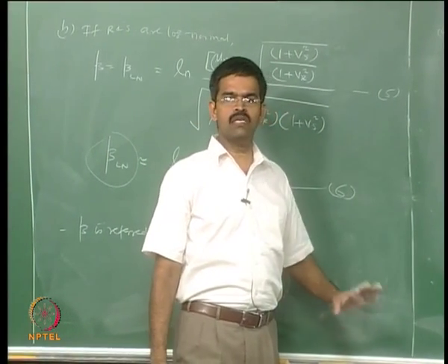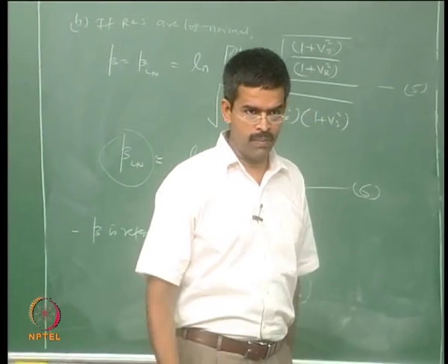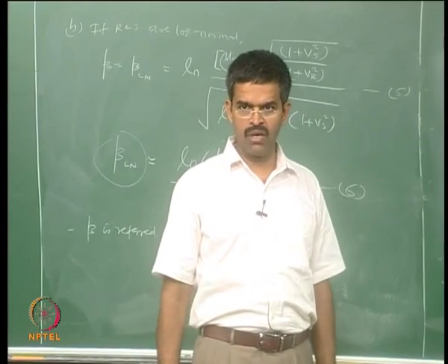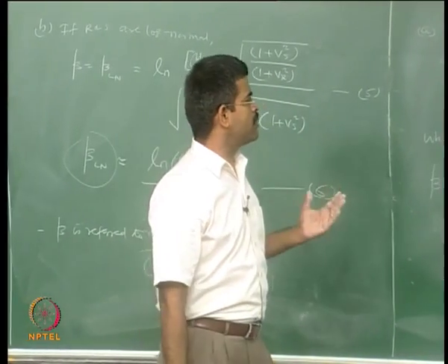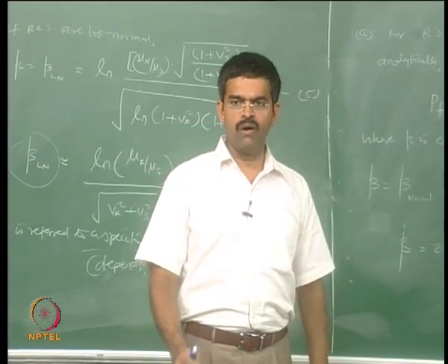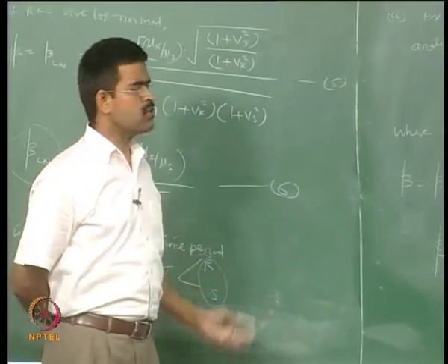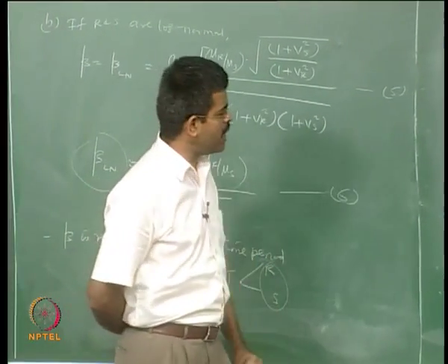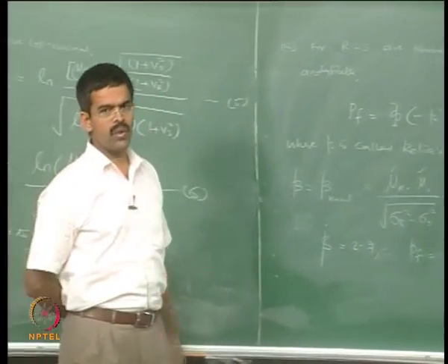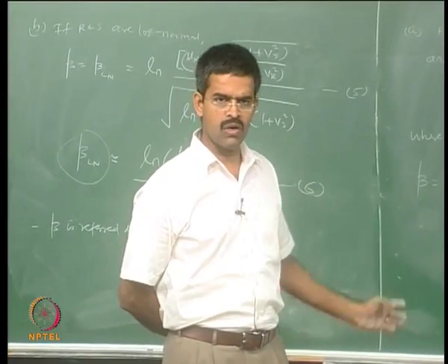So, how are uncertainties addressed in this, and why probability of failure in a time variant problem cannot be 100% accurate. Solution to this equation cannot be exact, because estimating the joint probability density function of a variable itself is a problem which we saw and discussed in this lecture. In this lecture we have understood how to estimate quickly for certain examples where my first order second moment parameters, that is mu R and sigma R, are available to me. Quickly, using a standard table of statistics, can I find out probability of failure. We saw this in this lecture.